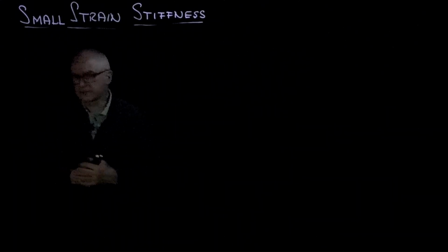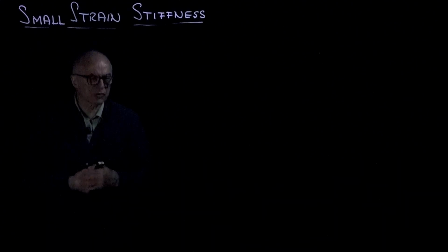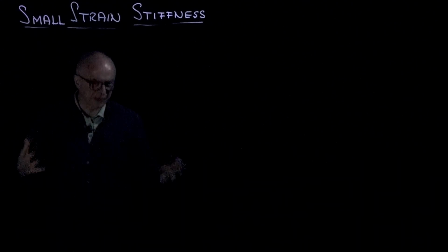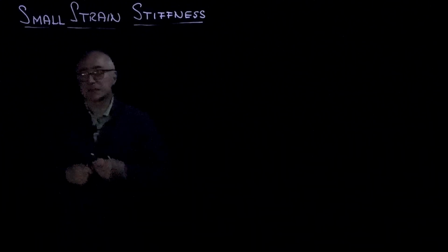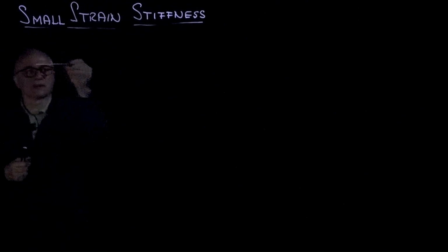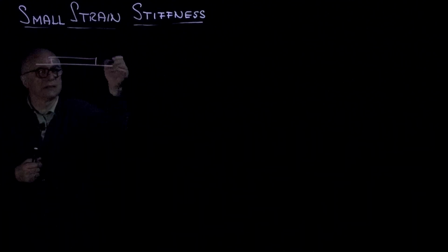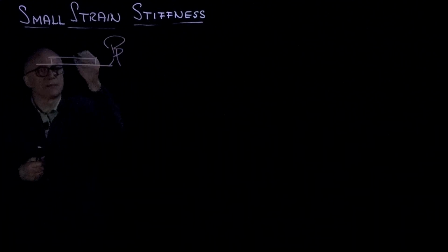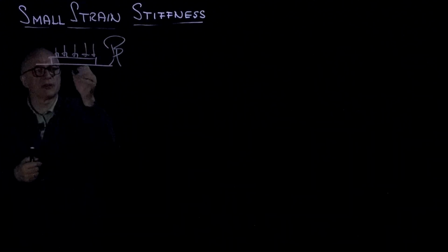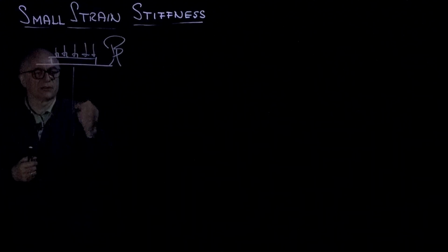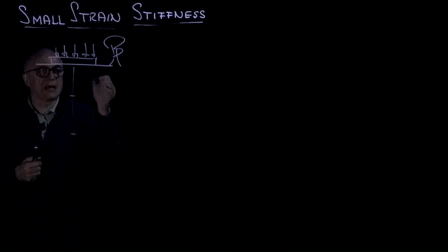The small strain stiffness controls the soil response in a large number of situations. Imagine, for example, we have the case of a foundation, and when we apply the load on that foundation, the deformations are going to increase in depth.